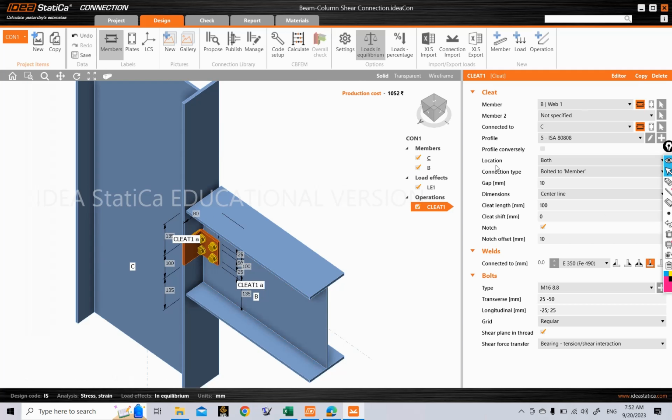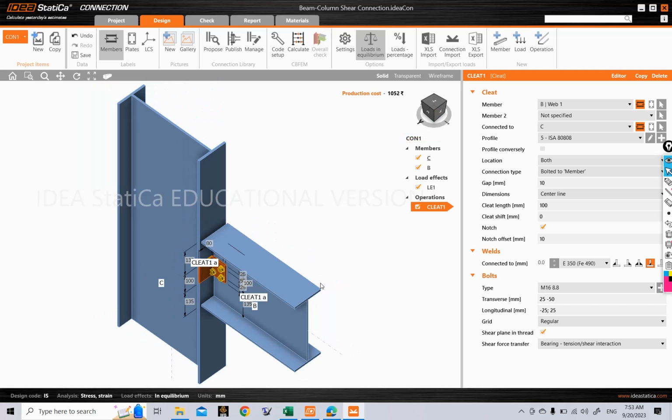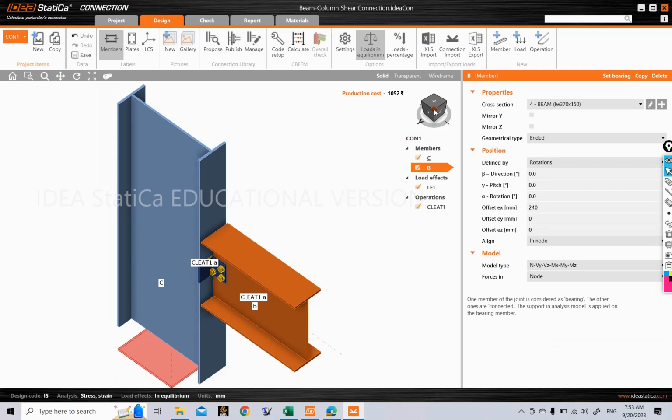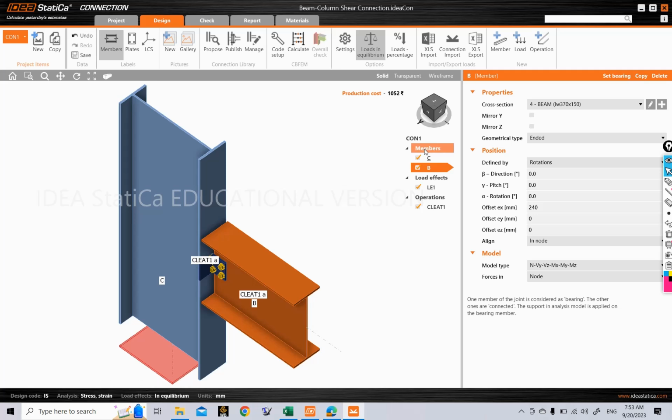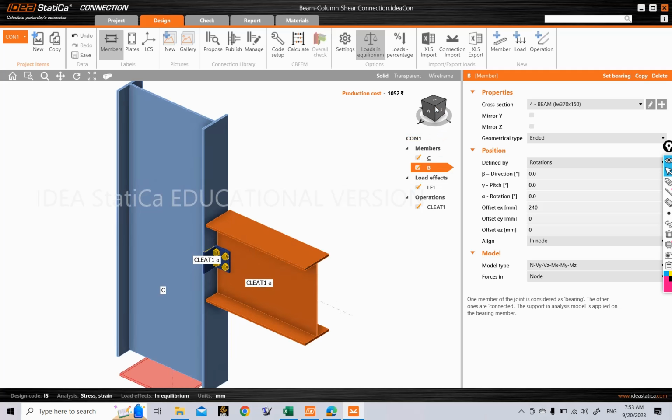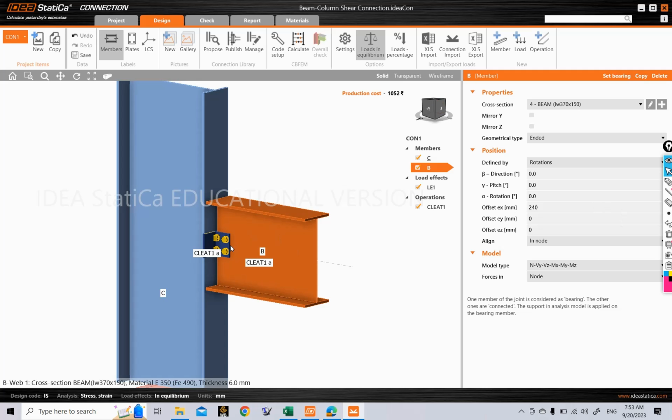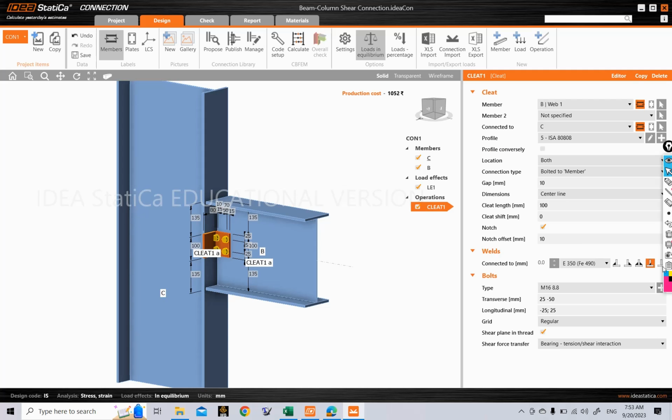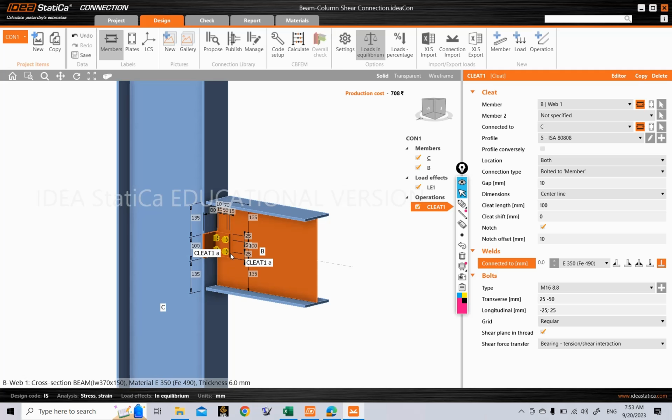So if you look at this option here, then there is no option to manually model the weld that we are using during our manual design. So what we will do is, currently in this Cleat option here, first we will suppose that there is no weld here, and then we will add a weld by ourselves. So check this no weld option here. Now there is no weld here.